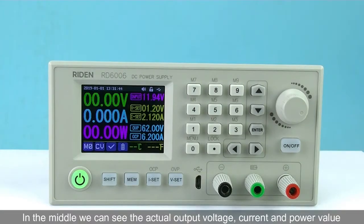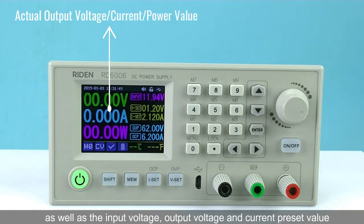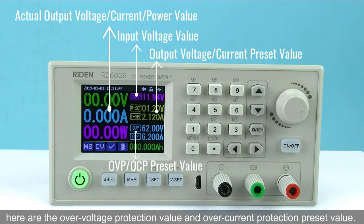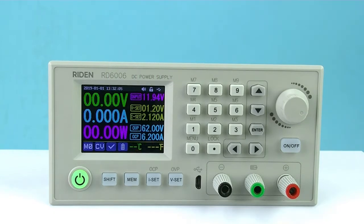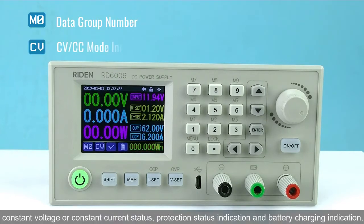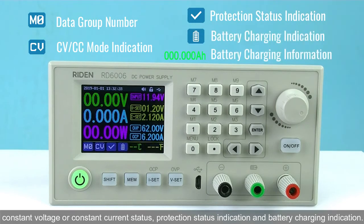In the middle, we can see the actual output voltage, current, and power value, as well as the input voltage, output voltage, and current preset value. Here, we can see the over voltage protection value and the over current protection value preset. At the bottom, we can see the data group number, constant voltage or constant current status, protection status indication, and battery charging information.